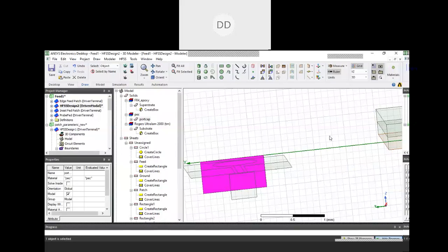Okay, let me try to address this way. The S parameter we give, like we have got one port and a second port. So the S parameter gives the property of the device which is connected between the two ports, port 1 and port 2. So in a transmission line or any other case, if we are able to model the transmission line first of all in HFSS, okay? Suppose you have got the model ready, and the next thing is, whatever you're using, you just place a port at one end, place a port at the other end, and try to check it out.